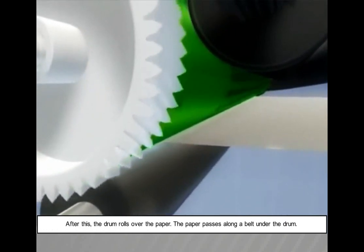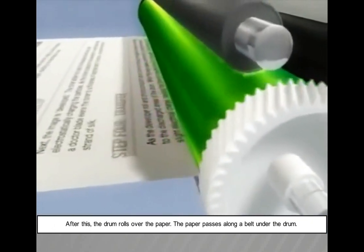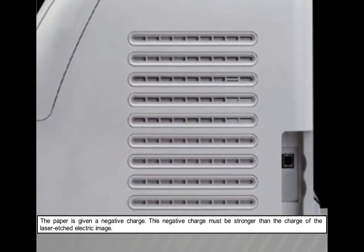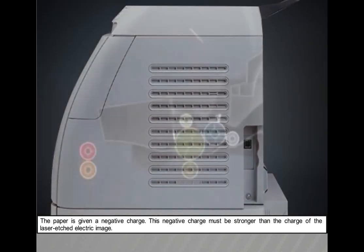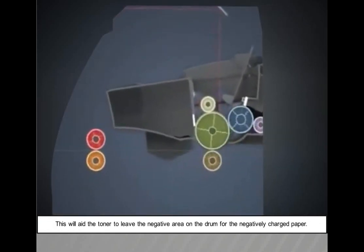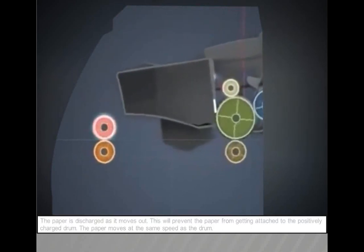After this, the drum rolls over the paper. The paper passes along a belt under the drum. The paper is given a negative charge. This negative charge must be stronger than the charge of the laser-etched electric image. This will aid the toner to leave the drum for the negatively charged paper.